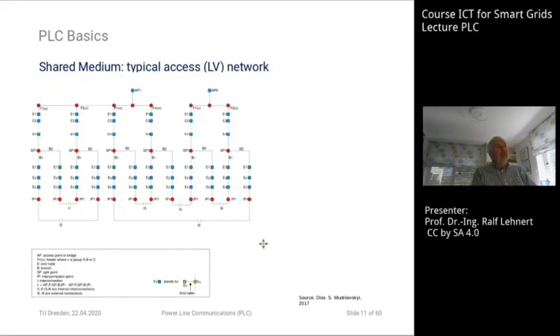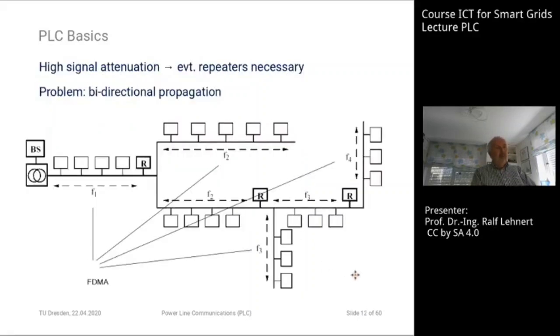So typically the low voltage network in city and suburban areas is a ring, which is usually open, but in the case of failure it is closing or even closing automatically, so there is no outage if we have just one link failure. And this is a typical example which we have been using in one of our research projects, and also it has been used by Mr. Modrzejewski.